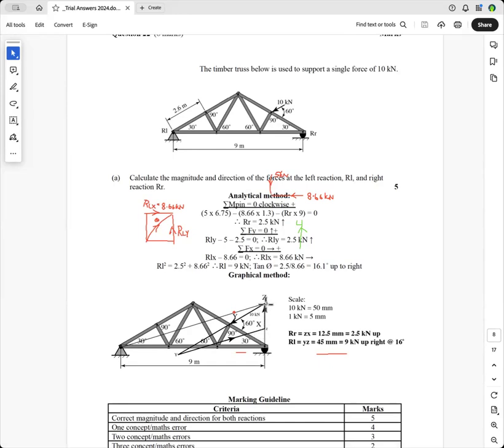So here's your forces here at the point of concurrence, and I've just used Bow's notation, X between those two forces, Y between that one, and Z goes all the way around here. And so you start with the known force, which is XY. There, I always start from the point of concurrence, then go clockwise.